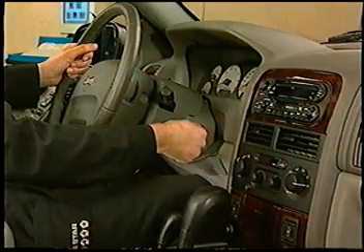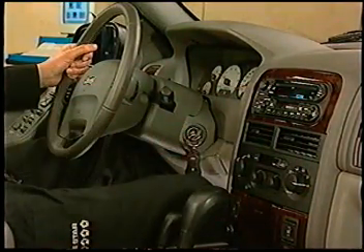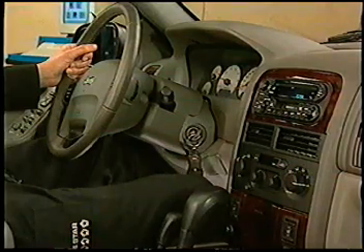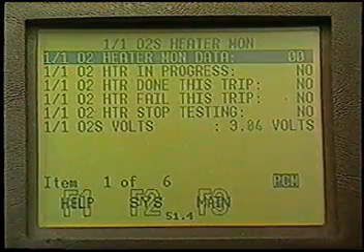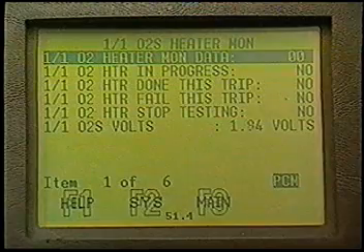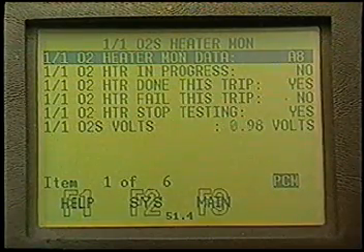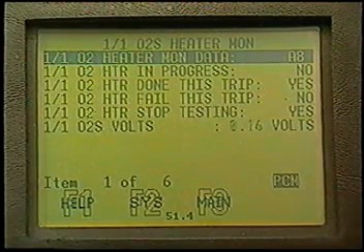However, on vehicles equipped with a JTEC, the test is performed on a cold start. At this time, the monitor looks for a change in diagnostic voltage to be below a certain threshold within a predetermined period of time. The next once-per-trip monitor checks EGR operation.